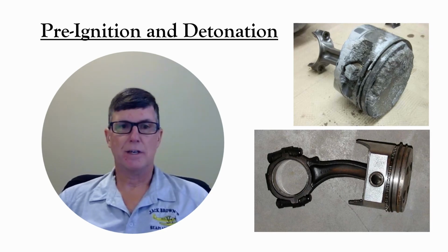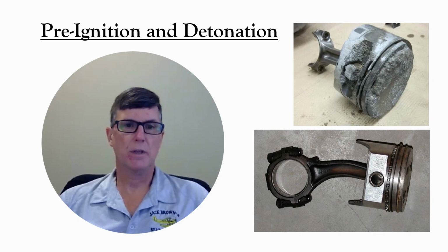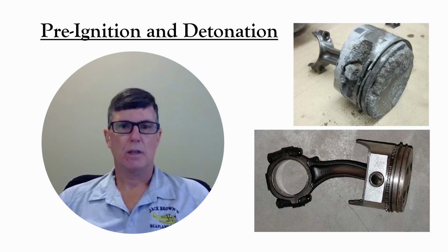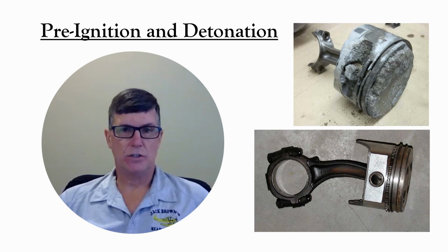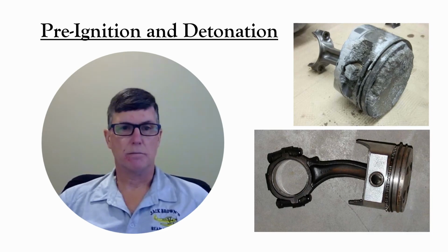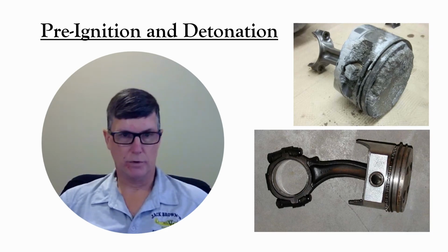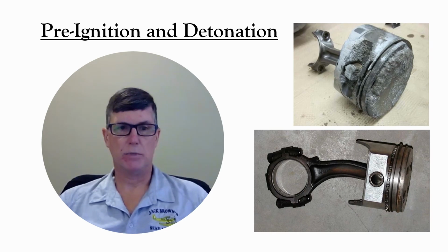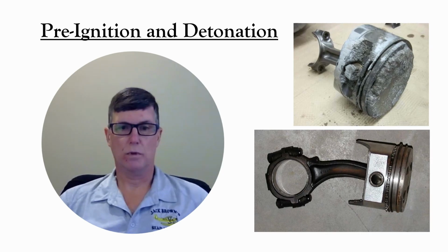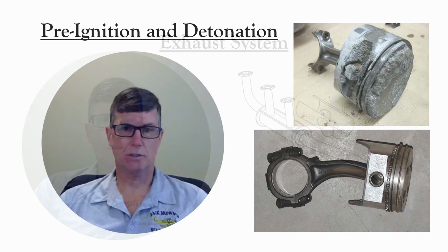Detonation is most likely to happen when you have a high manifold pressure and low engine speed. Using lower octane fuel makes detonation more likely. It will show up on your engine gauges as a rapid increase in cylinder head temperature. If it happens, reducing power is the best way to resolve it. If you have a constant speed propeller, increasing engine speed will help to resolve detonation.